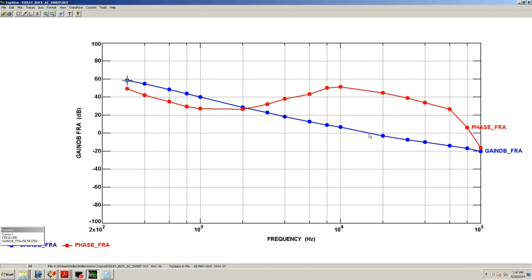So now it's crossing at about 16 or 17 kilohertz, while the relay was crossing at 20, and the phase is around 46, about 46 degrees. Okay, well, there really was 60. So it's a much better improvement.